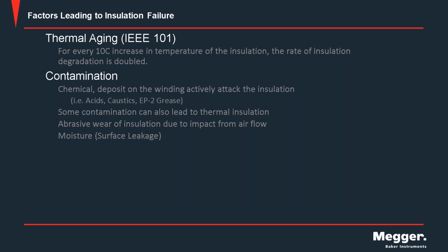Abrasive wear, those of you that are in the cement industry or coal crushing, right? That really abrasive material gets in the airstream and causes the insulation to degrade physically, right? So we literally sandblast, if you will, away the insulation till in some cases bare copper is exposed, and of course you're going to have a ground path at that point.